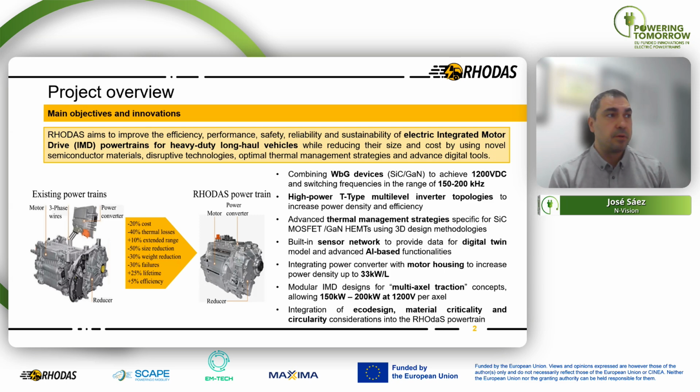The main objective of the RHODaS project is to do some research and development in order to develop a new integrated motor drive for heavy-duty vehicles. So the idea is to provide some technological advance that leverages the main advantages that wide bandgap semiconductors like silicon carbide and gallium nitride can provide, and also some innovative multi-level inverter topologies like T-type, in order to improve the integrated motor drive efficiency and also to increase the operating voltage and the switching frequency.